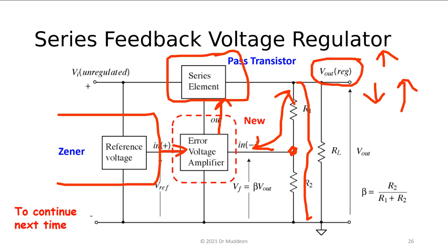So things have to happen every time the clock changes, either the rising edge or the level. Our charge cycle here, remember the capacitor is charging and discharging because of the wall voltage, which is a 60 hertz signal or a 50 hertz signal. In the case of the half-wave rectifier, it charges every 1/60th of a second. Or in the case of the full wave, it charges every 1/120th of a second because it's twice as fast. Make sense?